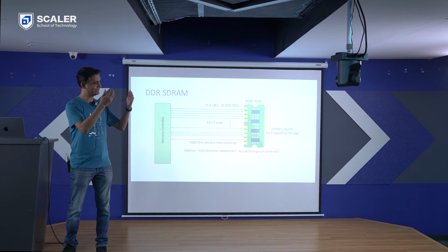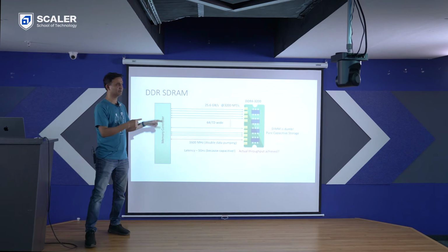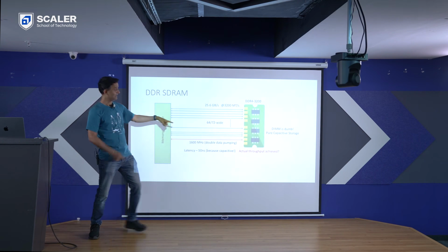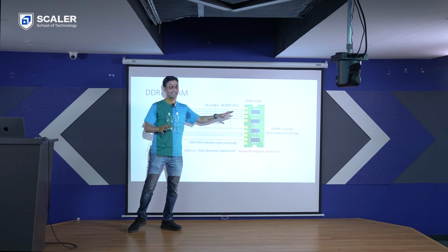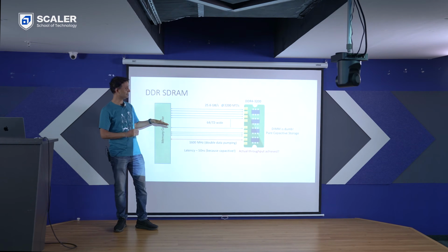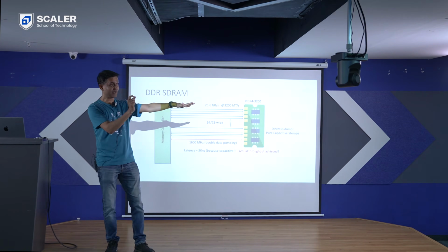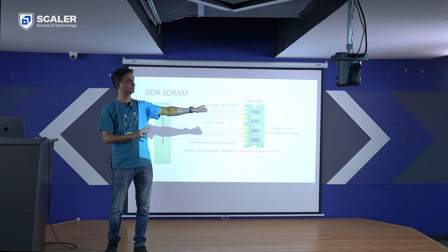But for the timing, let's park it for now. Let's assume that there's no hazard. What is the issue with pipelining? Can we pipeline in DRAM here in the way that I was describing? Remember, DRAM was dumb. Okay. Now I cannot detail it out without getting into some of how DRAM internally functions. But the point is, some of these control lines, memory controller needs to keep it on for a particular read to complete. So I cannot send another request in, just like that.